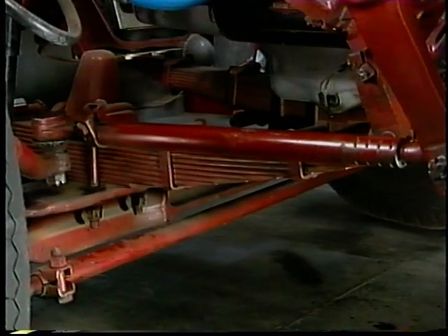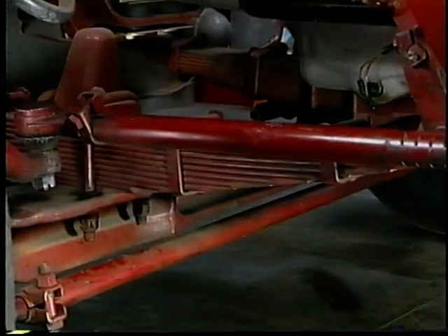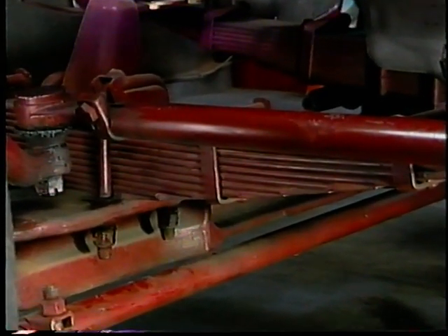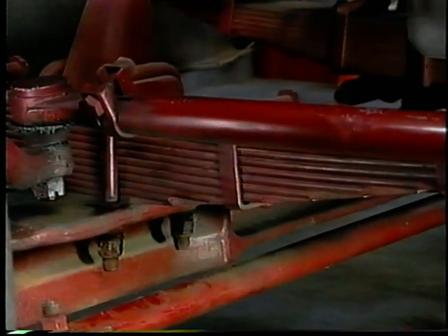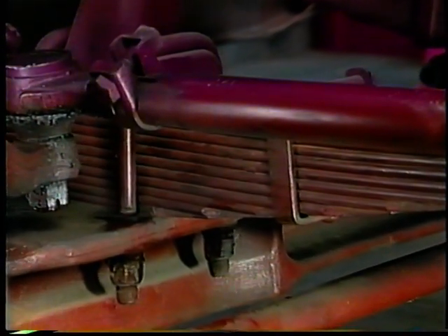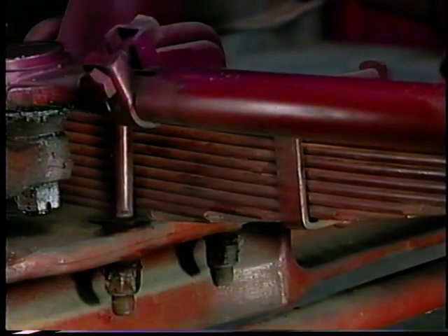Leaf springs are used to lower the center of gravity of the axle load by placing the I-beam below the axle center line. Problems with springs are usually noise-related or can affect handling by causing the vehicle to sway. Broken springs or cracked leaves will cause uneven vehicle height side to side.